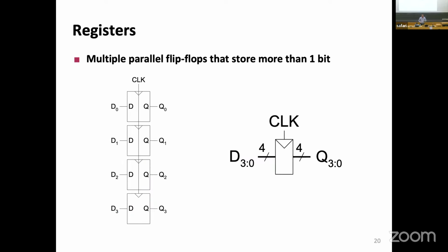let's stay under this assumption and move ahead a little bit, because in this lecture I want to talk more about what we can do with these flip-flops. One flip-flop is 1 bit. One lousy, tiny bit. You cannot even enter your grades with that. So you would want multiple flip-flops, so I can combine multiple bits together and have states that do more than just store 1 bit. The moment we have multiple bits, we usually end up calling them registers. It's a very loose term, register. Basically, it's a collection of flip-flops.